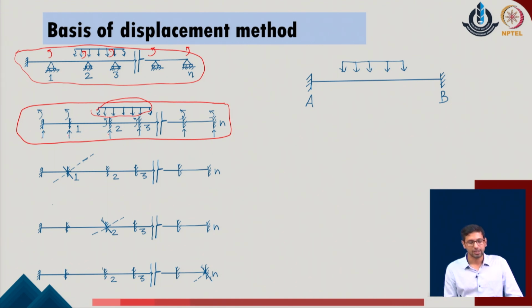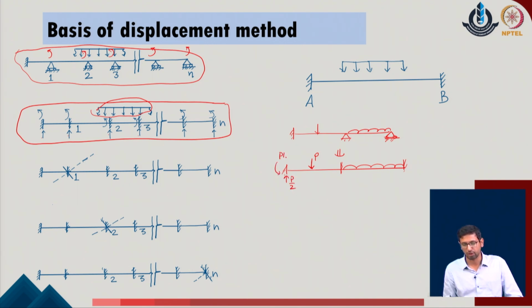Now, as we have already discussed, this part of the reaction calculation is much easier. One can simply consider it as an example case, like if I have this as an original problem and this member is subjected to these two kinds of loading, as a first step I will convert my system into the fully constrained system like this, subjected to this reaction and this load over the given system. Now, the reaction which will appear in this system will be only due to this span load of the given member. So, if this is the load P, this value will be P by 2. The moment over here will be PL upon 8 as per the given calculation. The reaction over here will be P by 2 again for the given system.